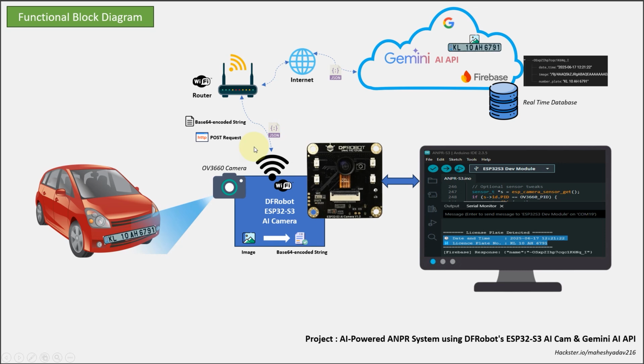it will send that JSON payload along with the natural language prompt by HTTP POST request, and we will get a response. The microcontroller extracts and parses that Gemini AI response, and we will get this output on the serial port. We are going to connect this MCU board to the Arduino IDE, and we will output all the extracted data on the serial port. You will get this type of response on the serial port.